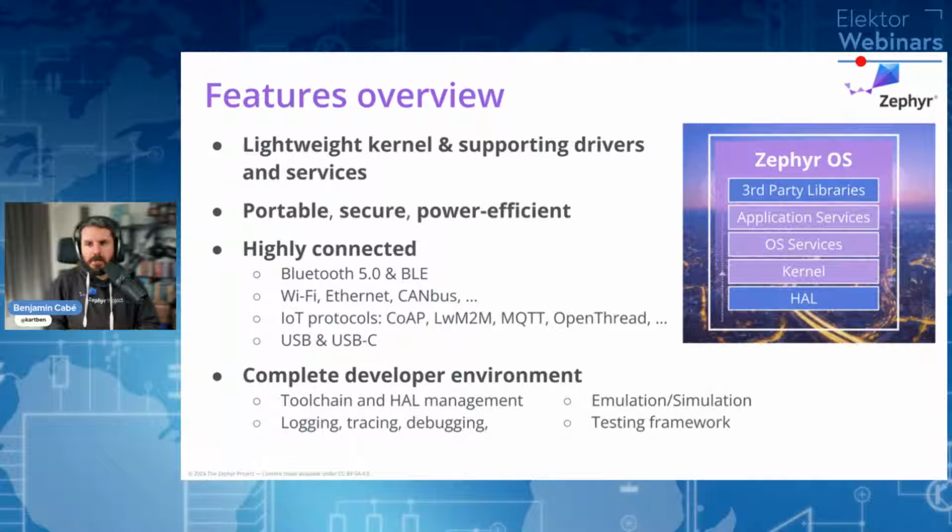Part of Zephyr is also helping you source third-party libraries like LVGL if you care about graphical user interfaces, or TensorFlow Lite for Microcontrollers if you care about TinyML, helping you basically source the actual third-party libraries that you may be interested in using in your embedded application. Make sure that they actually work well. Make sure that you can easily configure all the compilation parameters, etc., and have everything really integrated.